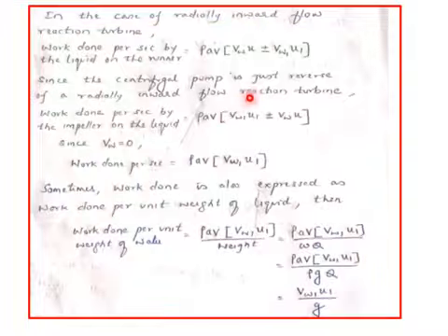Since the centrifugal pump is just the reverse of the inward reaction flow turbine, here the water enters at the inner circumference and moves towards the outer circumference. Whereas in the radial inward flow, water enters at the outer and moves towards the inner circumference. So there the work is done by the water on the impeller or runner, but here work is done by the impeller on the liquid. Therefore you can reverse this: inlet can become outlet and outlet can become inlet.